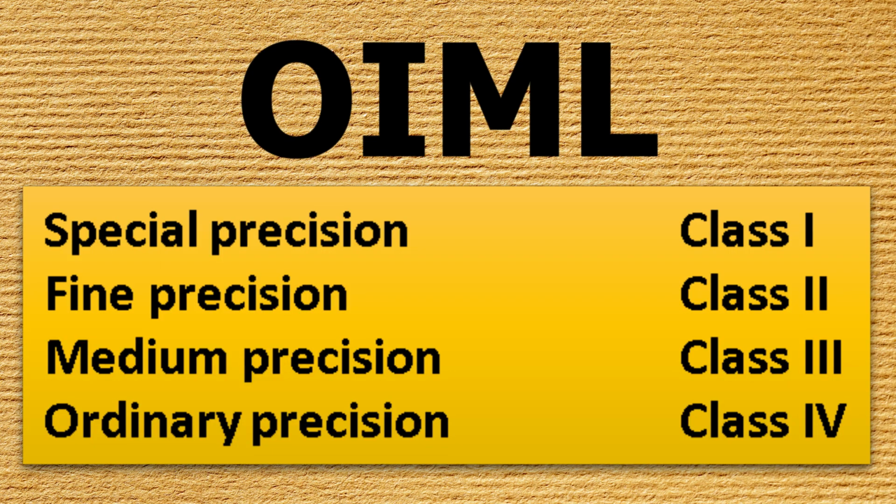The load cell is the sealed and encapsulated assembly of the bridge and the gauges, provided with mechanical fixing points to join it to the structure, being suitable for most industrial weighing applications. In weighing instruments, the metrological standards of the OIML, International Organization of Legal Metrology, are applied, which classify the devices into 4 categories, which you can see on the screen.